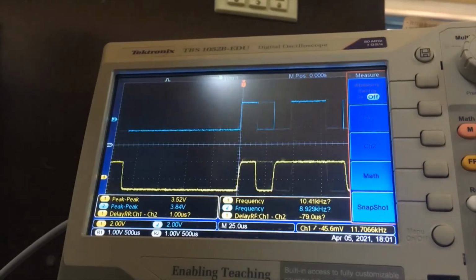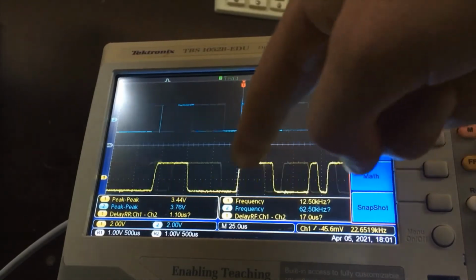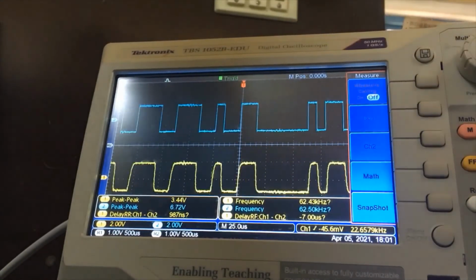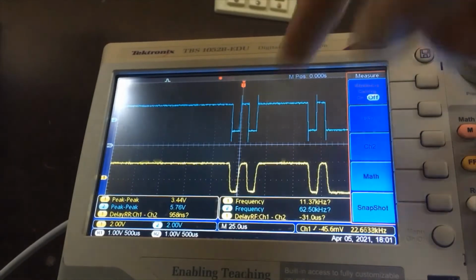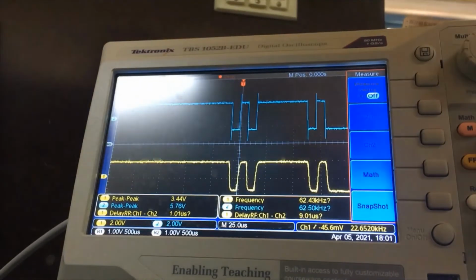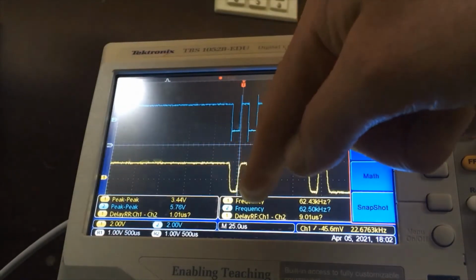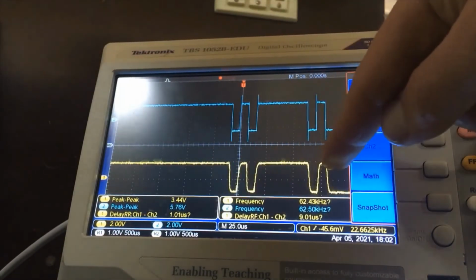If I further increase the sampling frequency to 16, you can see again the curve is changing. If I stop it, you can see that, from the Fourier knowledge, the higher frequencies are missing now in the received signal.